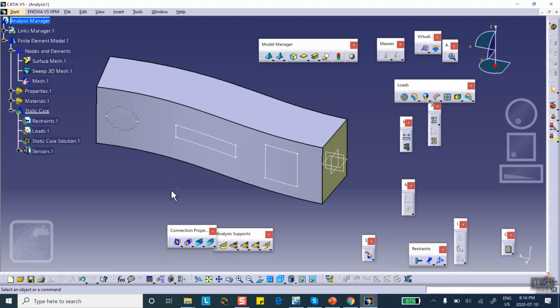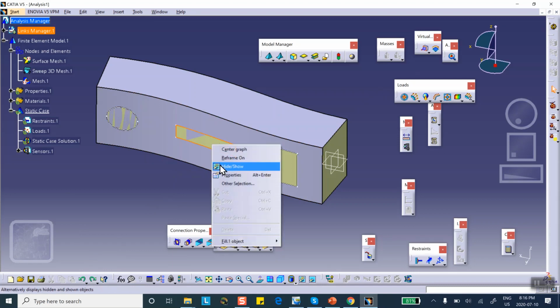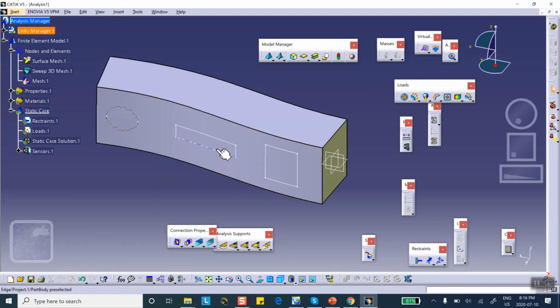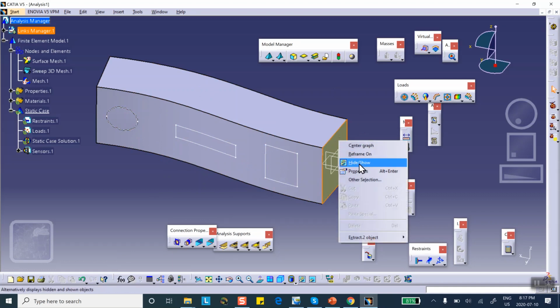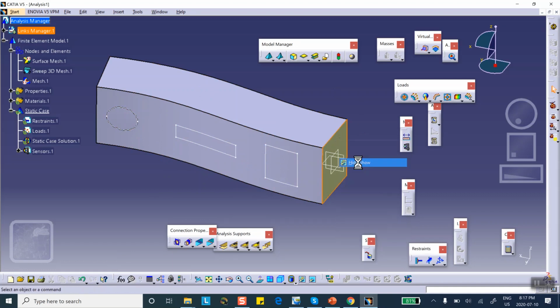Right, none of these things I need them anymore, so I just hit it. Let me undo it. These are the surfaces. These are the fill operation that I showed. Right click, hide. Okay, there are features created here. You can see that I can pick it. You can actually pick these things. Okay, and I'm going to hide this end surface that was extracted to. Remember, the sole purpose of that was to be able to measure it and then doing a sweep operation.